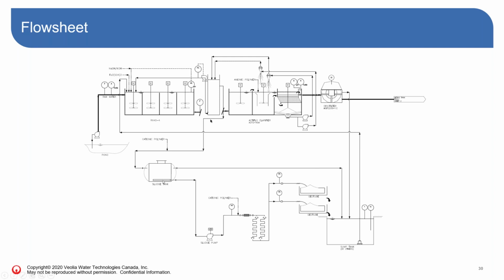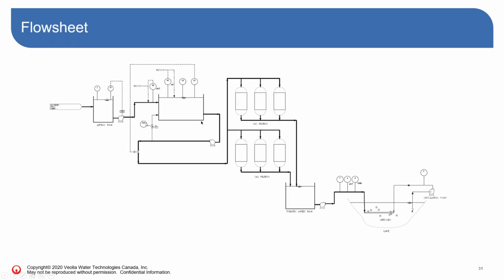In this case, it's a simple system with a sludge tank and then cationic polymer and geotubes, so nothing very fancy, but it actually worked very well. And then on the next page, pH correction and GAC filters, and then everything was returned back into the environment.